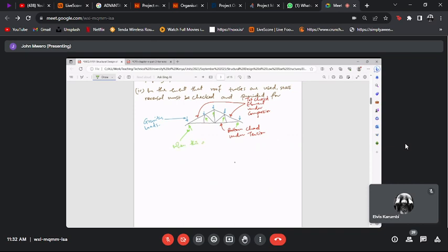When this exceeds gravity loads, the top and bottom chord would change to tension and compression respectively, such that now instead of the truss bending downwards, it's now trying to bend upwards.